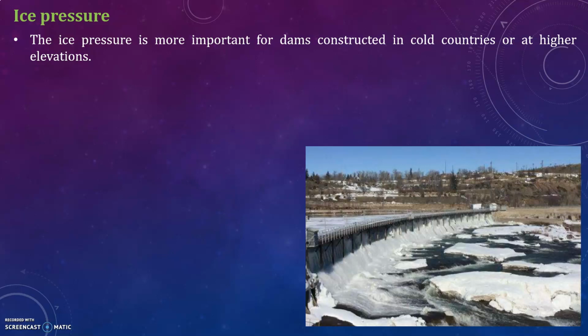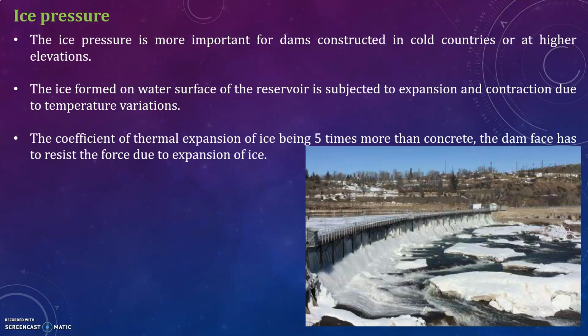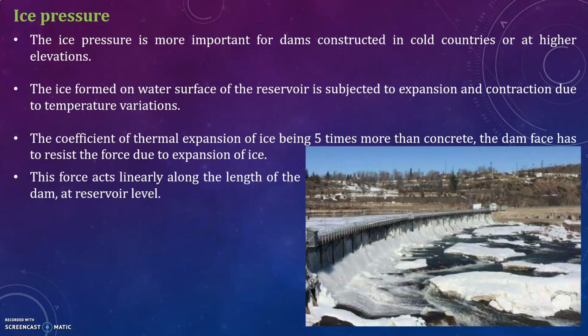The ice pressure is more important for dams constructed in cold countries or at higher elevations. The ice formed on the water surface of the reservoir is subjected to expansion and contraction due to temperature variations. The coefficient of thermal expansion of ice being 5 times more than that of concrete, the dam face has to resist the force due to expansion of ice.